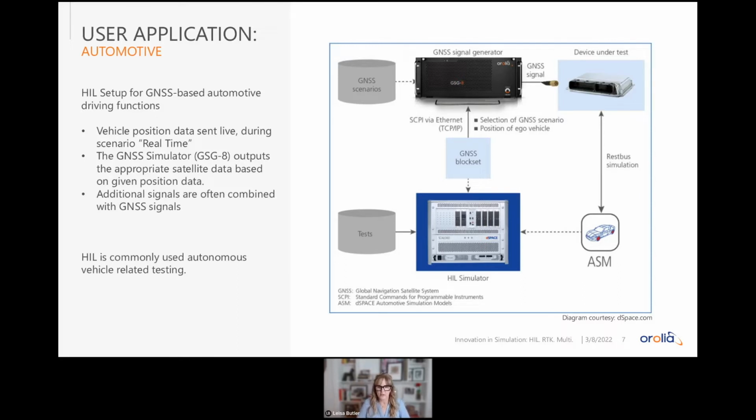So if you look at the HIL simulator, which is the background in blue, it is what is driving the whole system. So it has the test platforms. It's sending the signals, the vehicle trajectory, the motions. So whether you want to, like I said before, accelerate, stop, turn left, turn right, whatever motion you want to do, it's sending it in real time to the signal generator, the GNSS simulator, and then it can send the RF to the device under test.